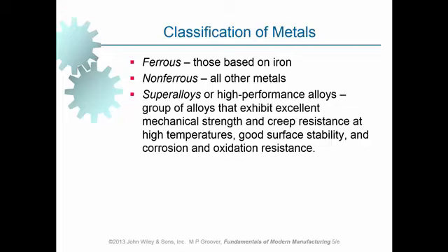In order to make this happen, we've got to make use of certain types of alloys in the material to make the material last at elevated temperature. And in some environments, when the possibility of oxidation is really high, we've got to make use of superalloys in order to make the product last long. And this is made possible by addition of high quantities of alloying elements in order to improve certain properties of metallic materials.